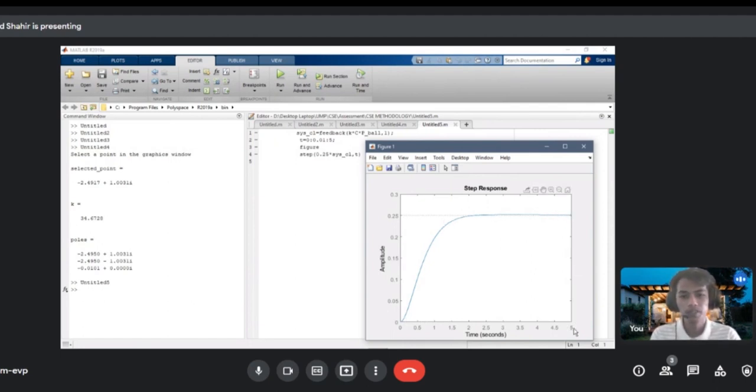A design problem does not necessarily have a unique answer. Using this method may result in many different compensators. Try running the M-file several more times, selecting a different point each time, and study the effect this has on the step response. For practice, go back to the original open root locus and try to find other ways to add zeros and poles to get a better response.